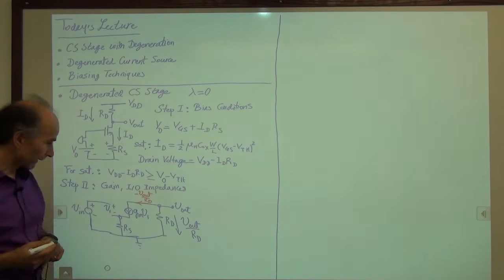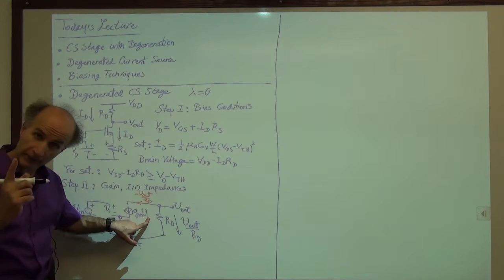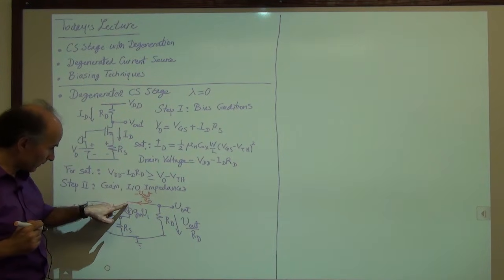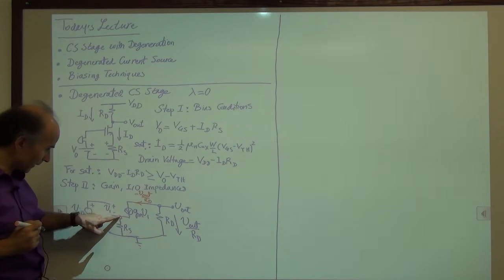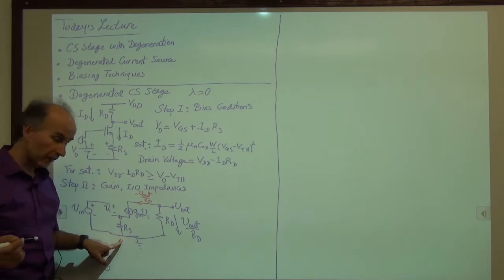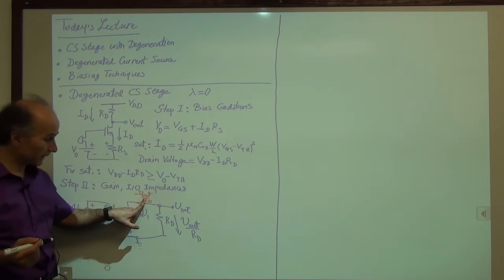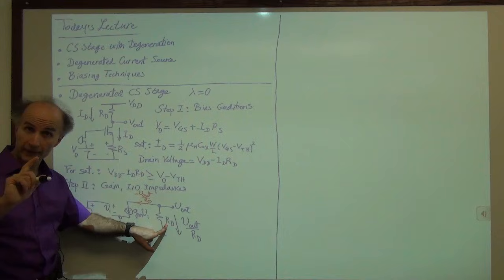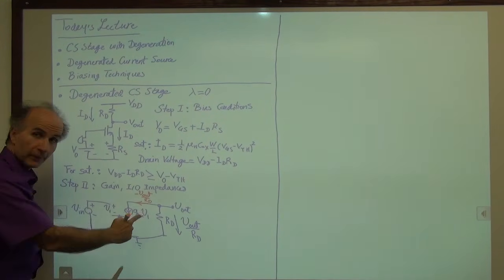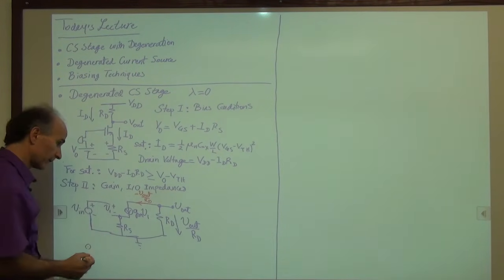Okay. All right, now this current happens to be equal to GMV1. So that's interesting. But there's also one other interesting point. This current flows through here, and flows through RS. It has nowhere else to go. So the current through RS happens to be this current, which is the same current as through RD, except with a negative sign. So RS and RD in this example carry the same small signal current, except for a negative sign.